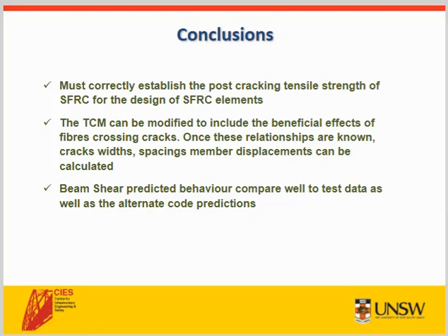And once we know or can quantify the tension stiffening relationship of fibre reinforced concrete, we can then determine with confidence things like crack widths, crack spacing, and deflections, which are all required for serviceability limit state design. Finally, beam shear was predicted reasonably well with models that we developed during this study.